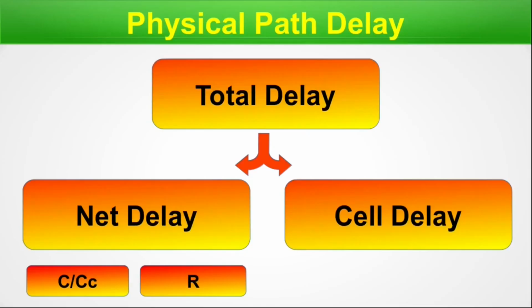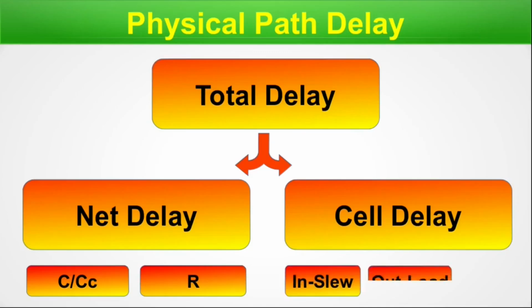The cell delay comes from the physical standard cells which have a circuit component as well as the metal 1 and metal 2 routing in each. So these cells are pre-characterized by the Liberty characterization tool to calculate input slew, output load, for various PVT corners. The cell delay varies from one type of cell to another type of cell. Also for the same cell, it varies when we change the cell height. As an example, I can say 6T, 7T, 9T and 12T. Here T means the metal track width. So when you deal with the standard cell, you come to know about the cell height, which is measured in terms of tracks.